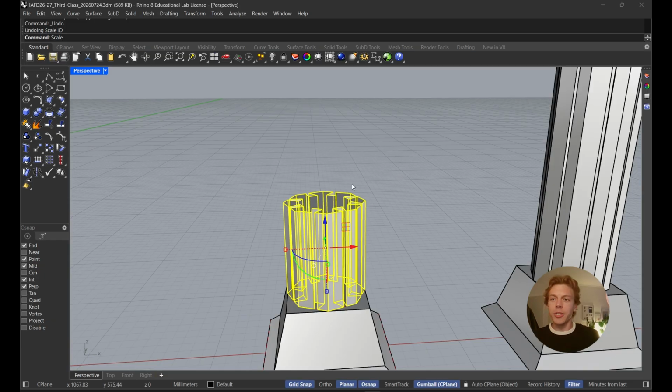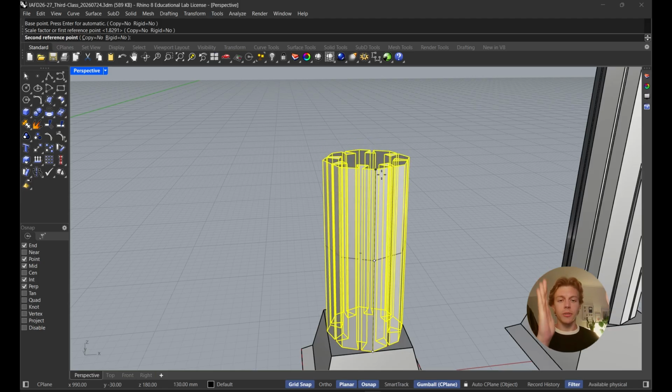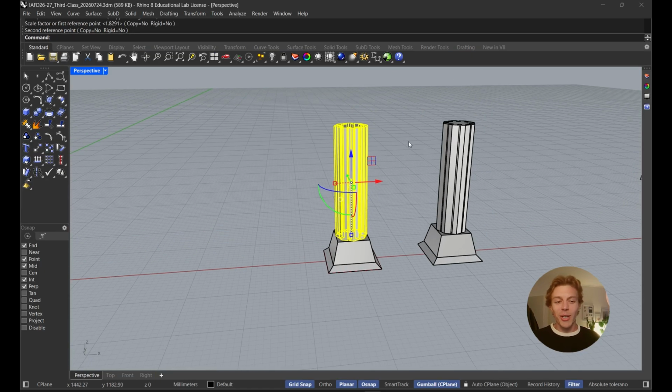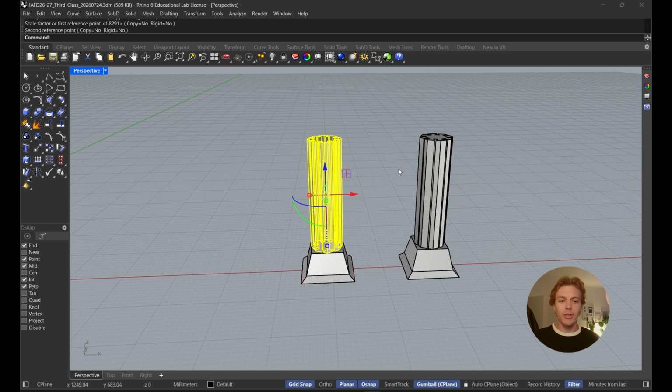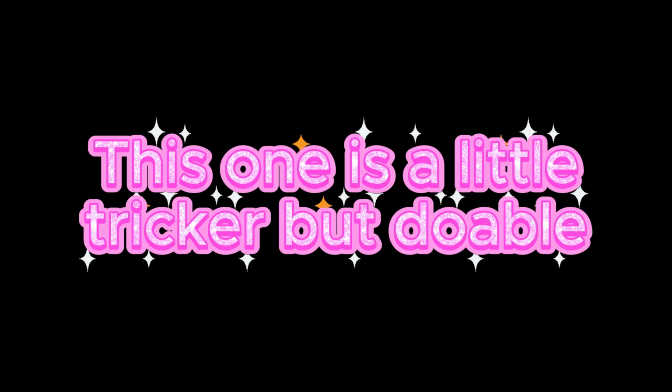So when you're using scale 1D or any scale command by chance, just always make sure that you're doing it in a straight line. If your intention is to create something crooked, that's also fine. But if you're trying to make a precise adjustment, usually a straight line will be the best option. And again, I'm going to give you a break that you can go and try it out yourself. And if you have any questions, just rewind the video.